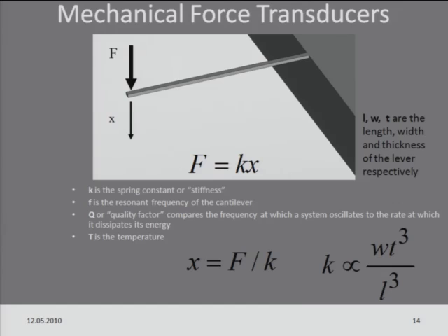Of course, if you think about the problem in a little bit more depth, you'll realize that when you want to measure very, very small forces, there's going to be another limit here, which is really thermodynamics. At some point, for small enough forces, the thermal force, or the Brownian motion of this cantilever, will start to limit you. So if you want to measure a force, that force better be bigger than the force that you get from just thermal excitations of the end of your cantilever.